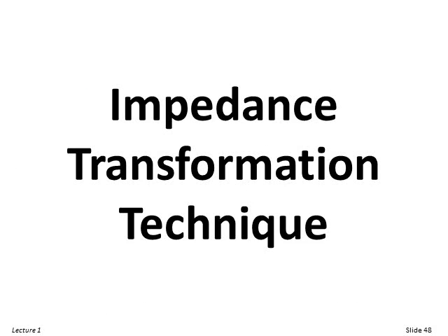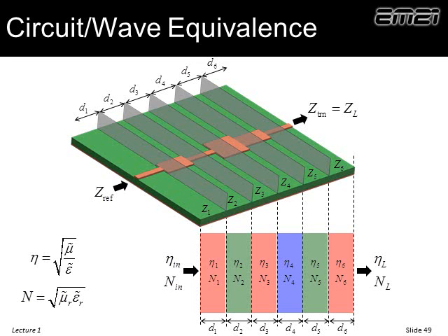And I'll leave you with a bonus thing that we may or may not do much with, but here's a different way of modeling reflection from a stack of layers. So let's say we have a transmission line circuit, and this looks like a microstrip. We have a ground plane on the bottom and our signal trace on the top. And depending on the width, we're controlling the impedance of that transmission line. So what we have are a bunch of segments with different impedances.